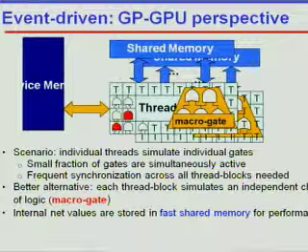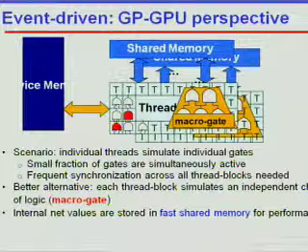From the GPU perspective, individual threads will simulate individual gates, and only a small fraction of gates are simultaneously active, and frequent synchronization across all threads is needed.